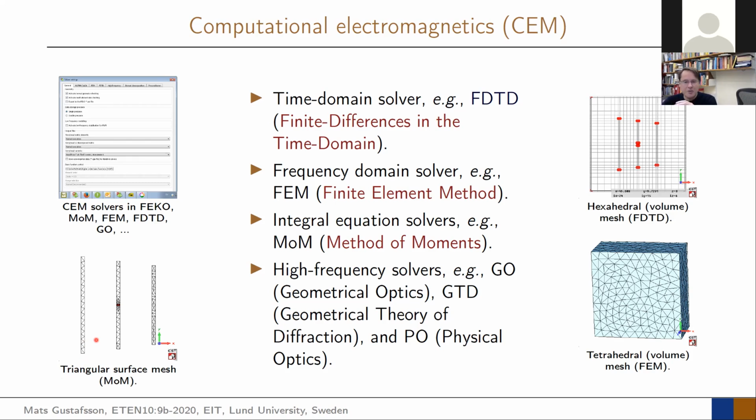So you always need to have sufficiently many sample points to be able to describe what is happening with your currents. And that's done with something called a mesh. The one you've been running for your patch antenna, and also in the cases for a lot of other structures, has typically been a surface mesh. It can also be a wire mesh. Both of them exist. And in those cases, each of these triangles is like one degree of freedom for your current.